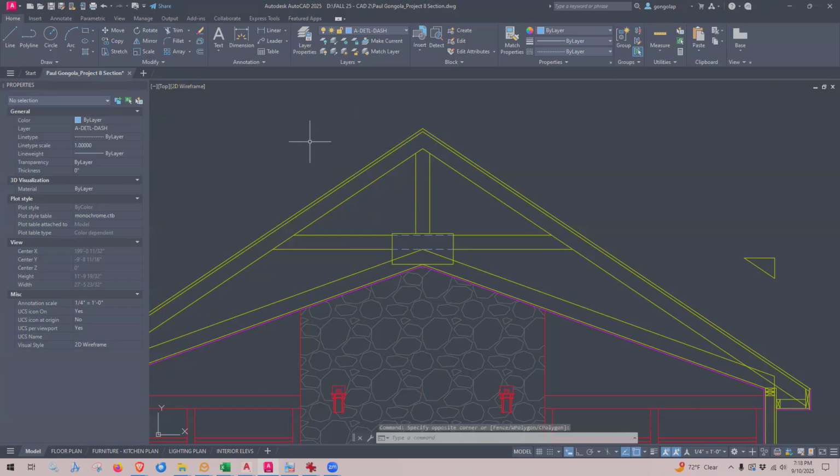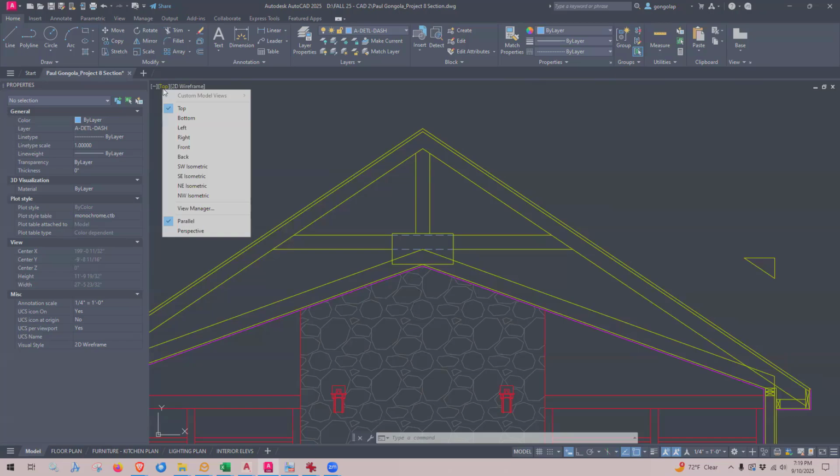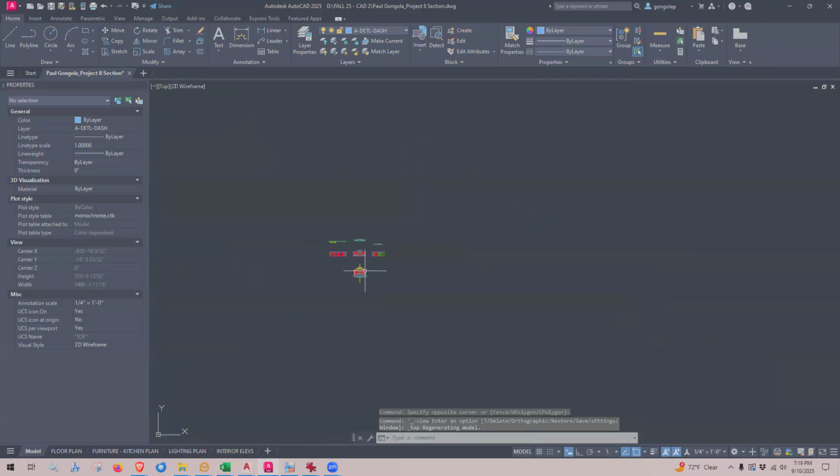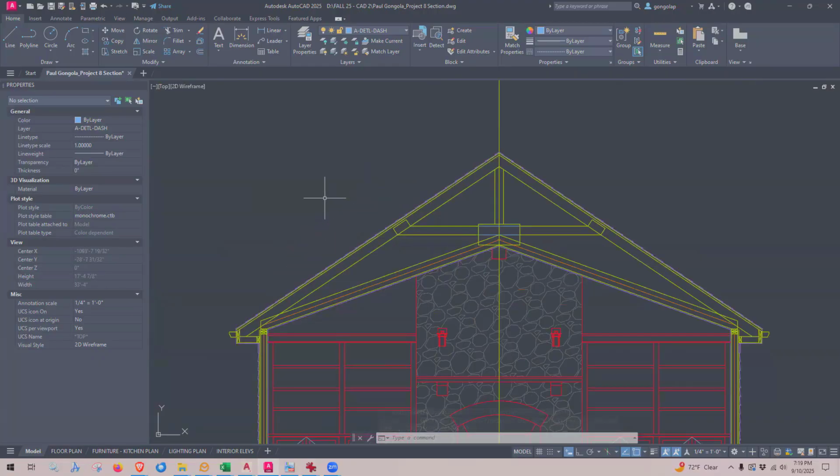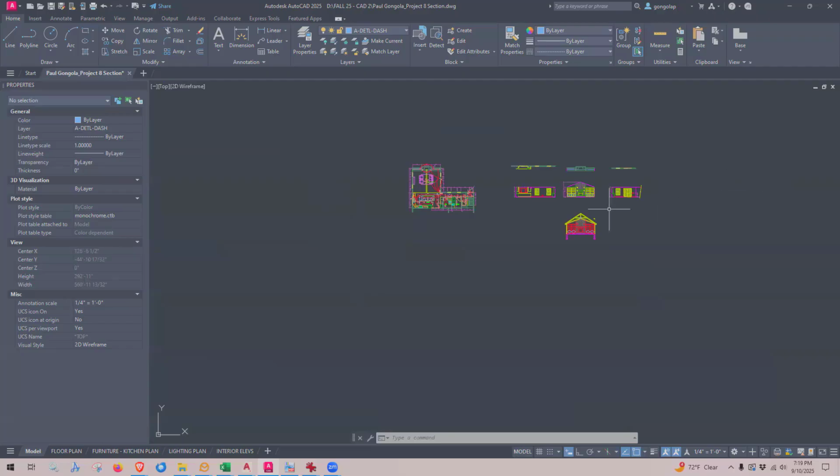It usually means you're drawing in 3 dimensions rather than flat. Has it been that way all evening? No, it just happened. And this says 2D wireframe. And does this say top? It says custom view. Instead of top, this says custom. Oh, I changed it to top and it went back. So click on top and change it to top. Okay, did it work? Yeah, it went back. It sometimes happens. Thank you.